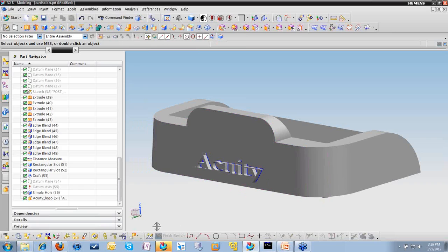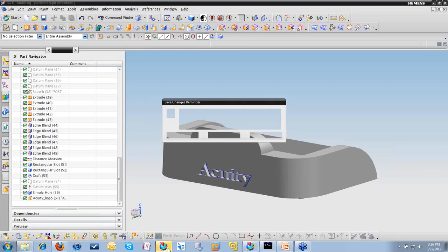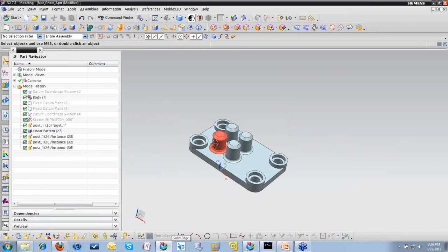I think that's pretty much all I wanted to show you guys. You can get really complicated with this stuff and push the limits. As you saw in that other example in NX7.5 that I was demonstrating, you can pick multiple features, and that's a huge benefit. Because just one extrusion is not going to really save you a bunch of time a lot of times. When you're grouping a bunch of these things together and saving yourself some time, that's where the power is right there. So with that said, that's pretty much all I wanted to present today.